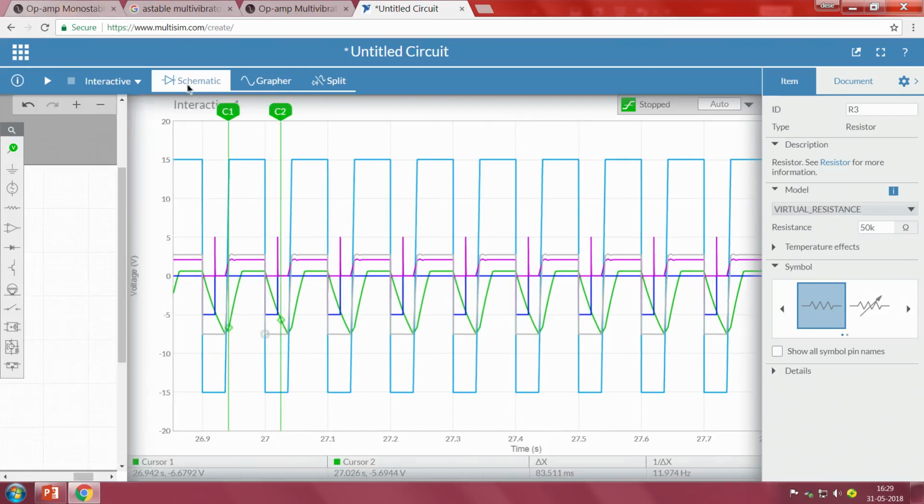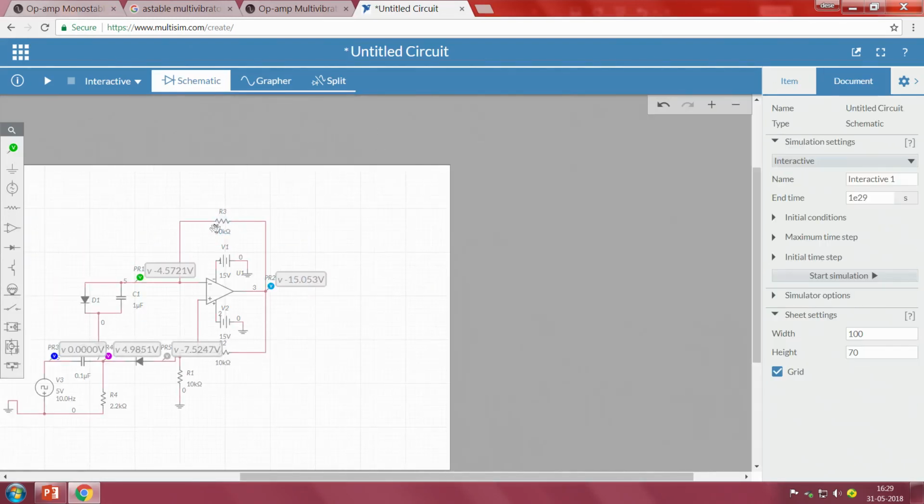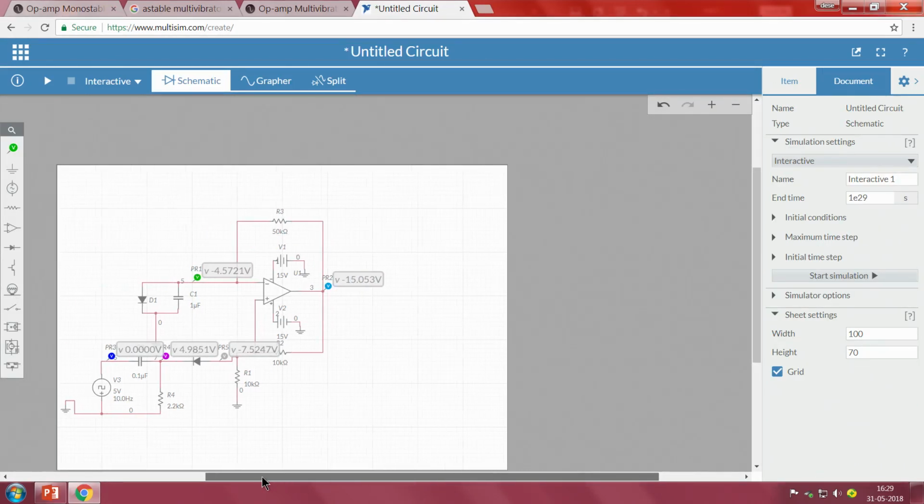So you can change the different values of resistance and observe that. Or you can even change the capacitance value, because RC entirely depends upon R and C. The multiplication factor is what is responsible there. I hope it is clear why we have used this differentiator. The purpose of the differentiator is that the square wave will be converted to a spike, which is a triggering input.